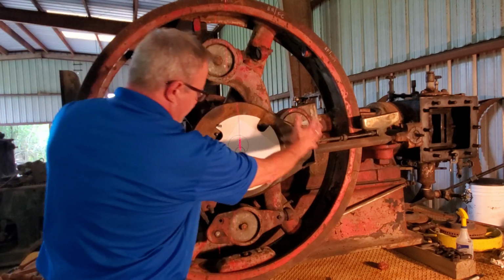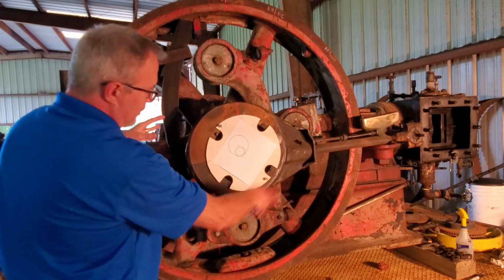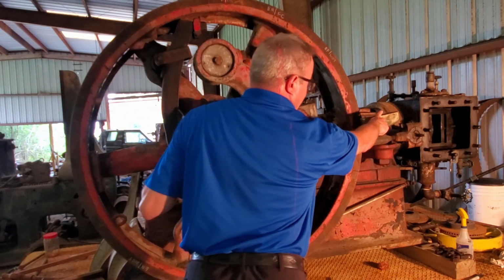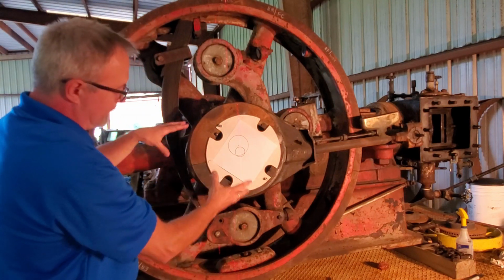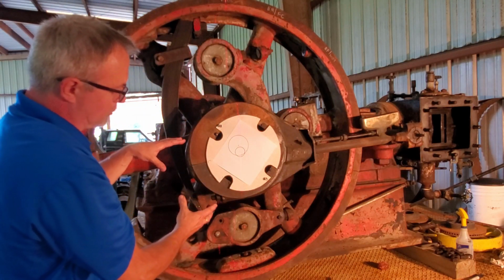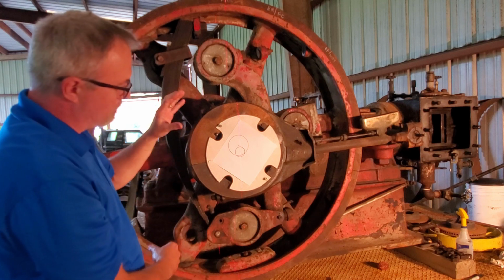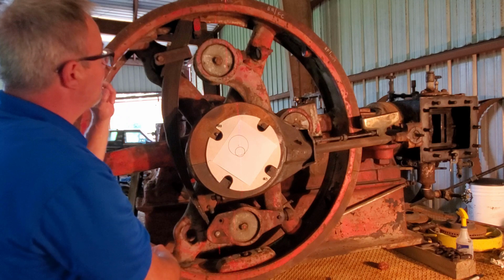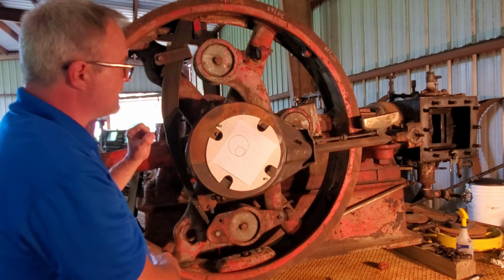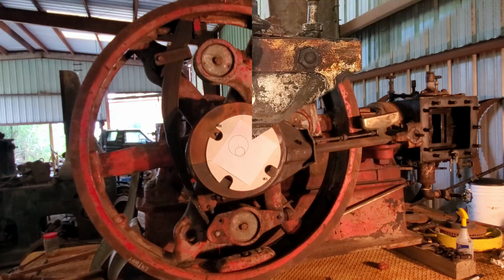This has a large steel guard to contain the oil splash, and it's fed from the oiler into this cavity, and all of that babbit surface is oiled by that system. So that's for way down the road when I have the machining capabilities to do it. But let's move on to the steam chest and slide valve.